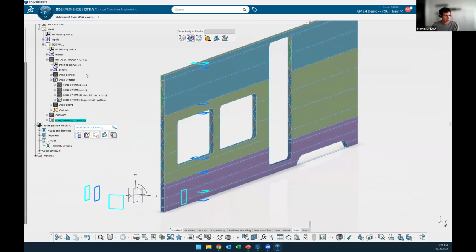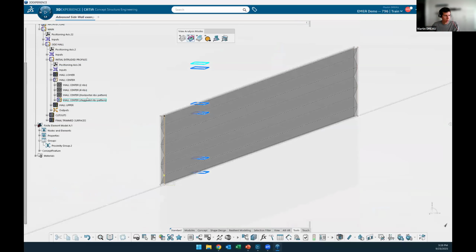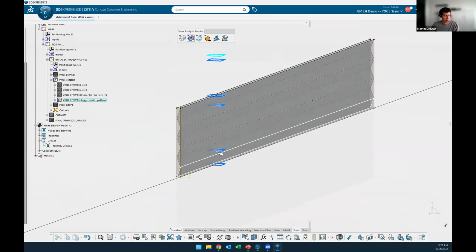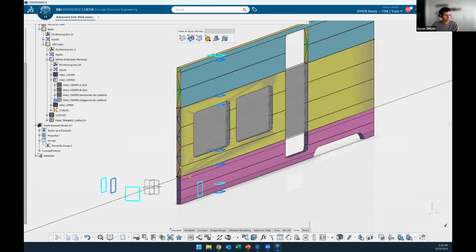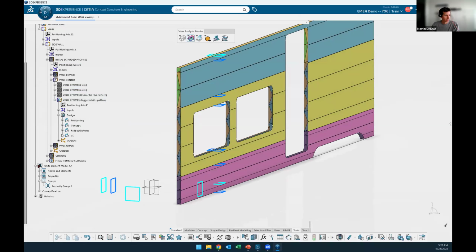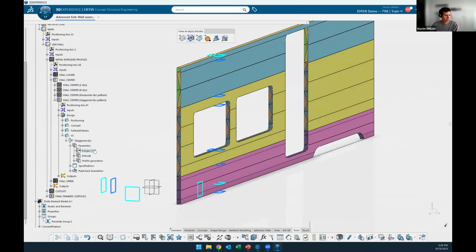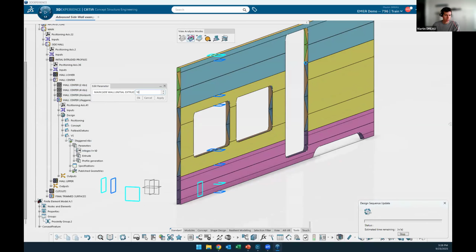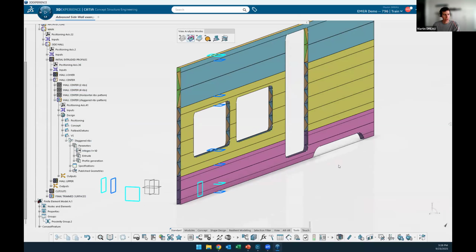If I visualize the modules I imported, it looks like that, and it's reconnected with the architecture. Even if we change the length or the width of the train car body, everything will reconnect automatically, again based on the module technology. And here I also have a parameter to change the number of ribs. It can go to 4, or to much more diagonal ribs. You see the number of diagonal ribs is automatically changing.